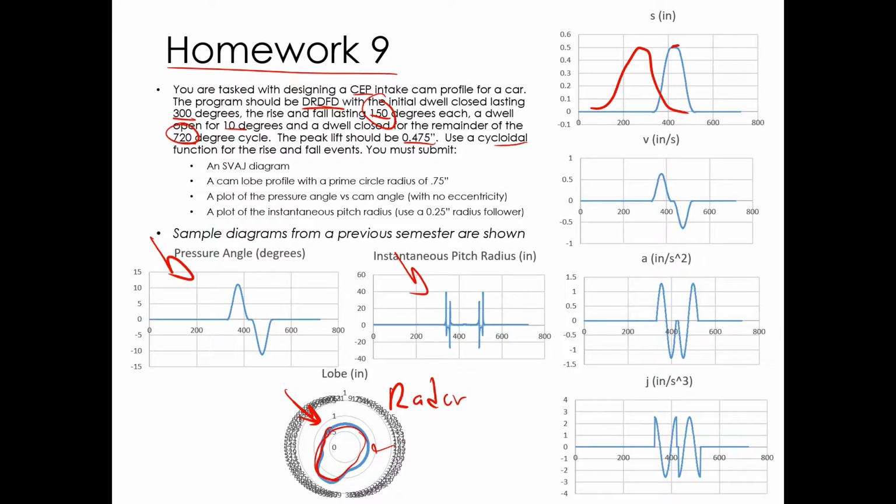This is a cycloidal function. So you'll have to go back to CAMS 2 and use the equations for the rise, and then also when you do the fall you'll have to make sure you use the modified equations for the fall. There's a slide on that.